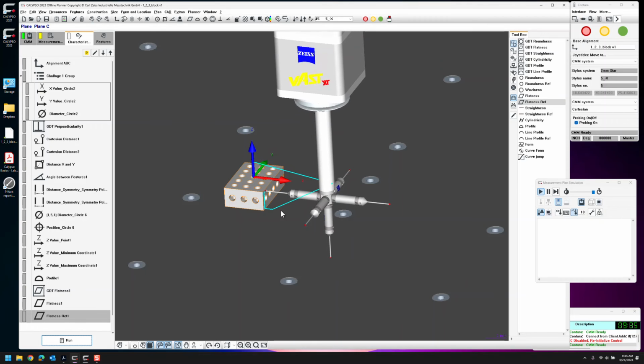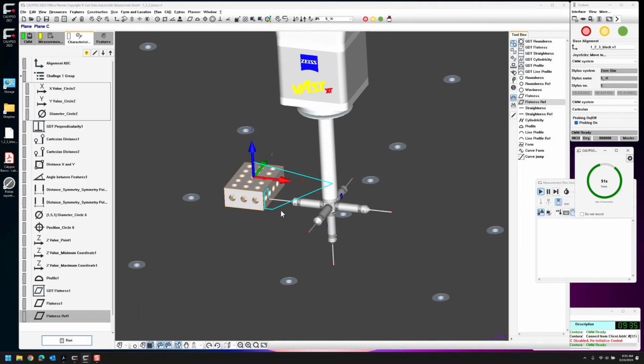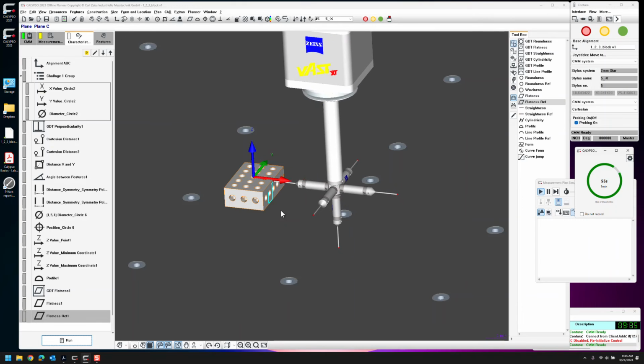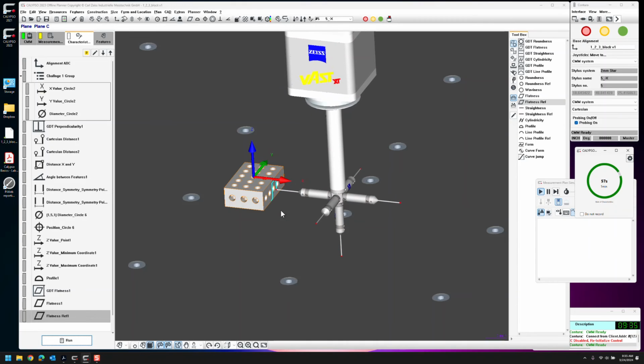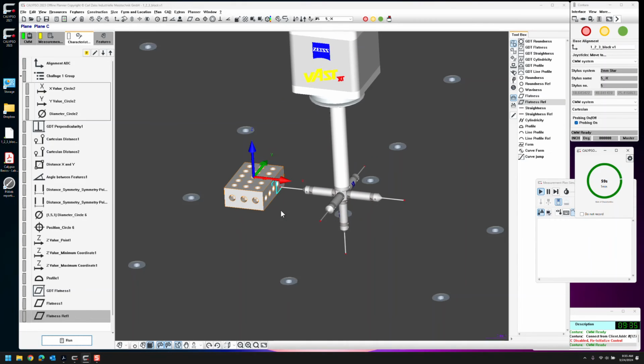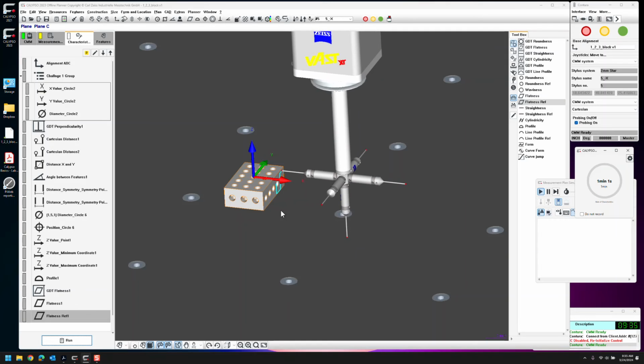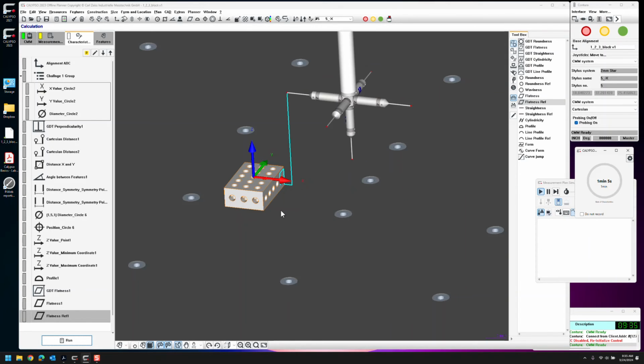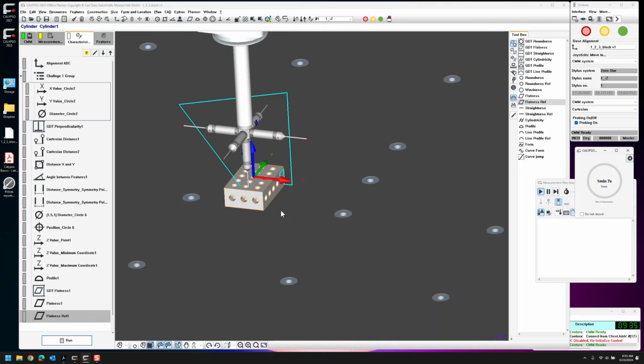When you go to speed up a measurement plan, what I generally do is start increasing the speed. If it's looking real slow, I might double the speed. Otherwise, I increase by 50% over the current level. But here's what you do: you run the program or run the feature and look at the standard deviation and the form, okay?